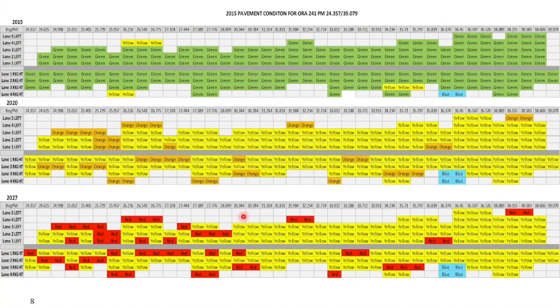That means structurally damaged. And for the rest, where you only have a little red, you may be able to do a localized dig-out type of treatment. And for the primary yellow, you may be able to do a thin overlay or chip seal type of thing. You can just fix it up with that. So that's the entire process of pavement management, at least in my mind.